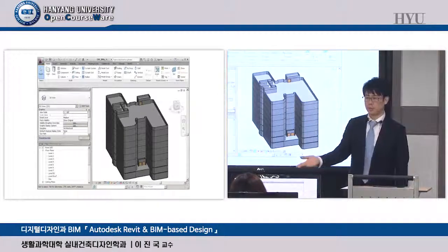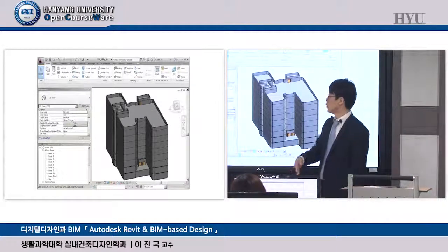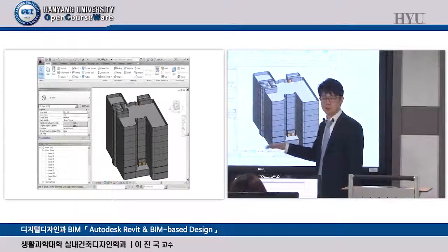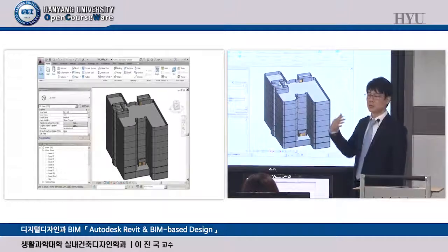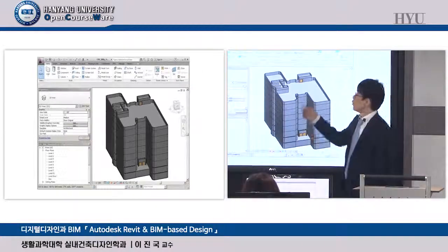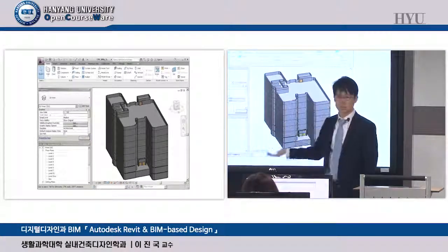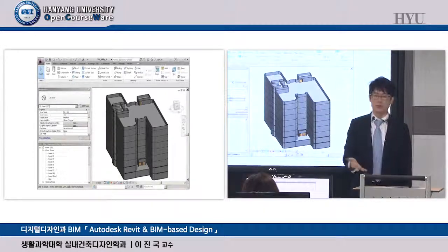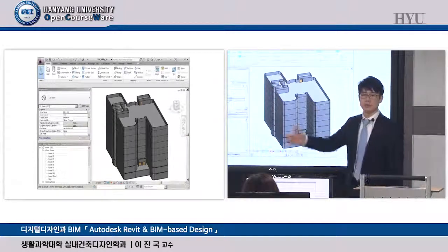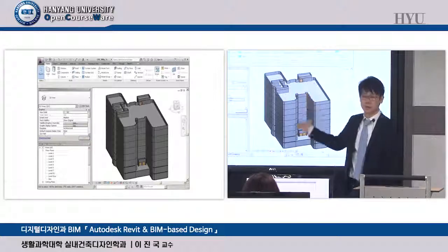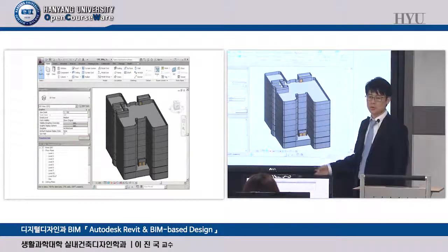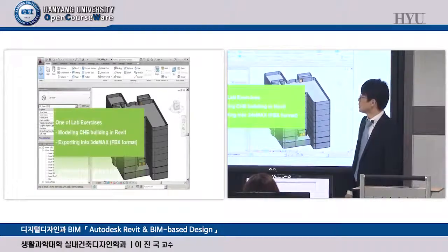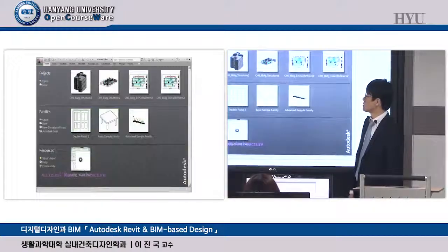You already copied it, okay? So what you need to do is open Revit, import the CAD file, draw walls and doors, and place windows, only using the given components, not custom objects. You don't need to download or create anything, just use the existing library. And then you can make this kind of structure today and next week for the lab exercise, okay?